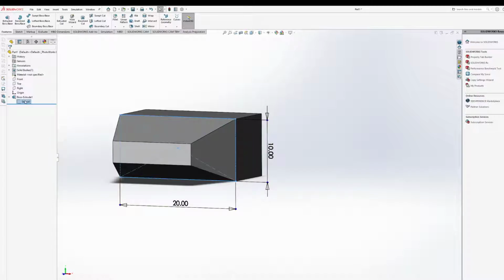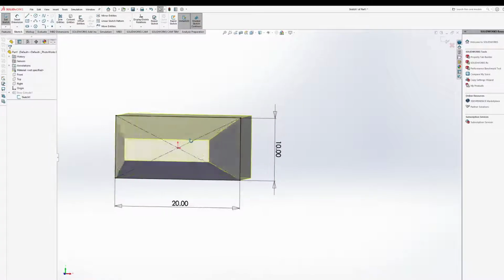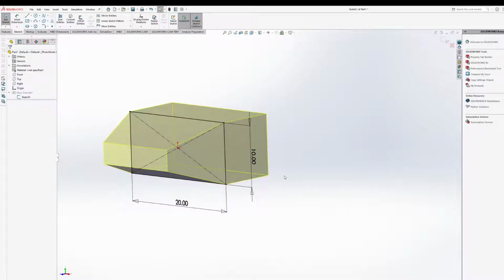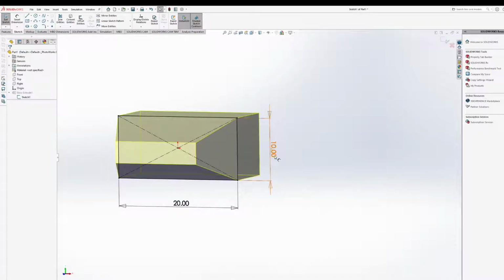The only thing I would have to do is right click on your sketch plane, hit the sketch button, and it'll automatically bring up the necessary dimensions. It'll still be showing that ghost image of your extrusion until you make any adjustments to it. But it's a good way of still showing you what's going on.